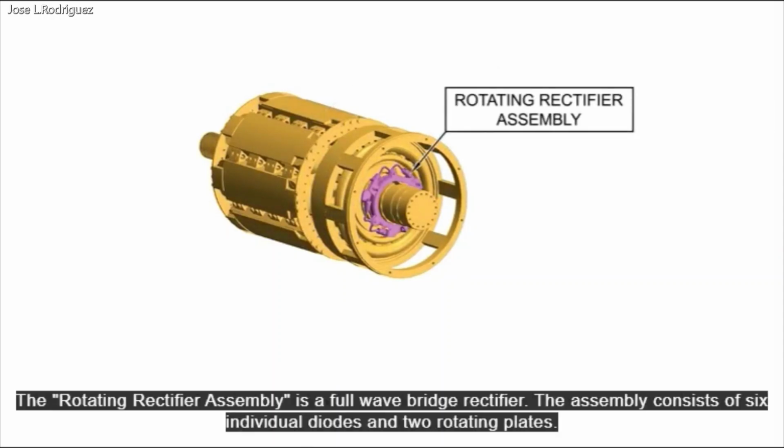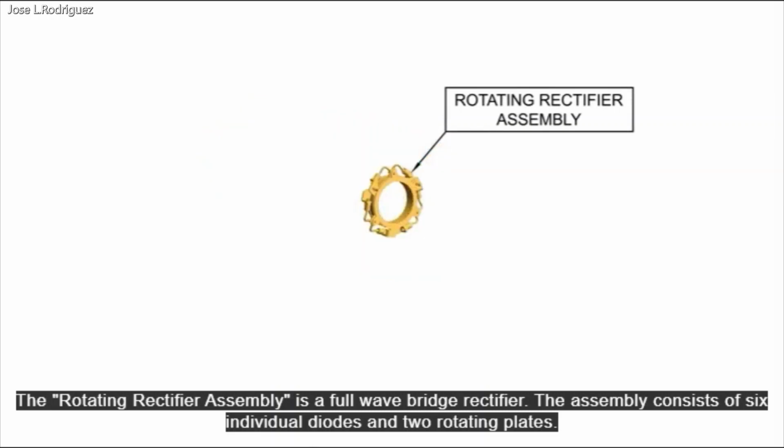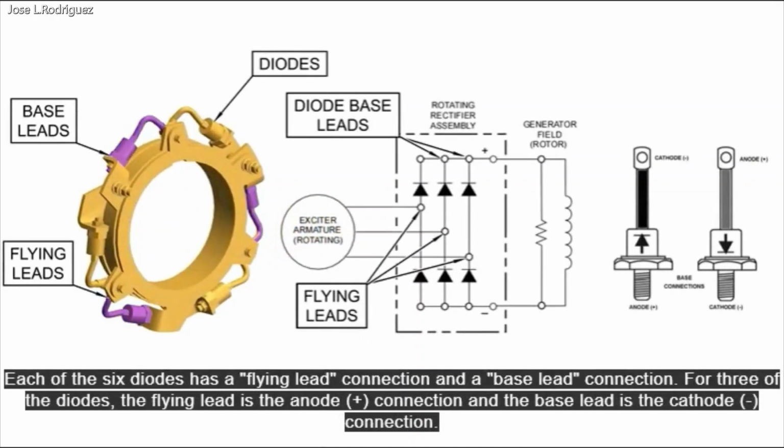The rotating rectifier assembly is a full-wave bridge rectifier. The assembly consists of 6 individual diodes and 2 rotating plates. Each of the 6 diodes has a flying lead connection and a base lead connection. For 3 of the diodes, the flying lead is the anode connection, and the base lead is the cathode connection.